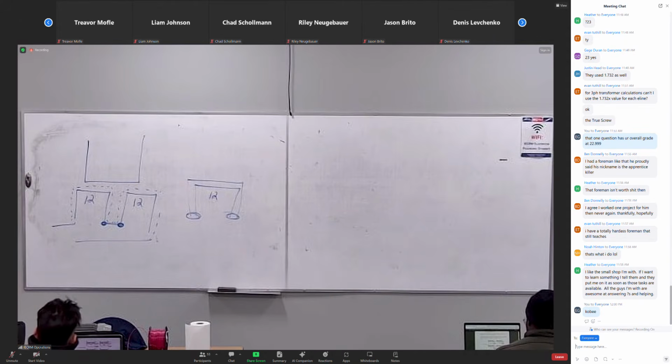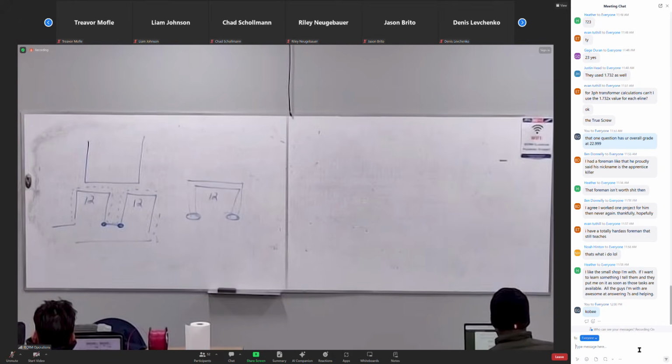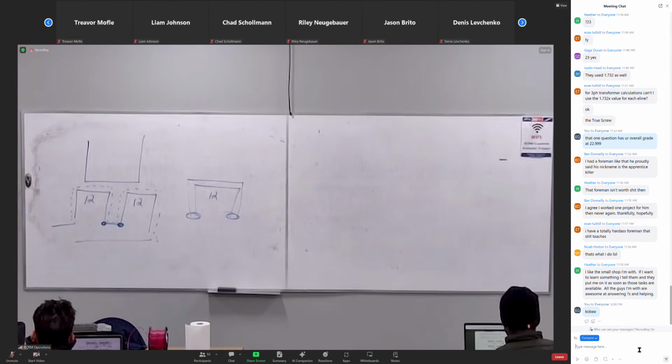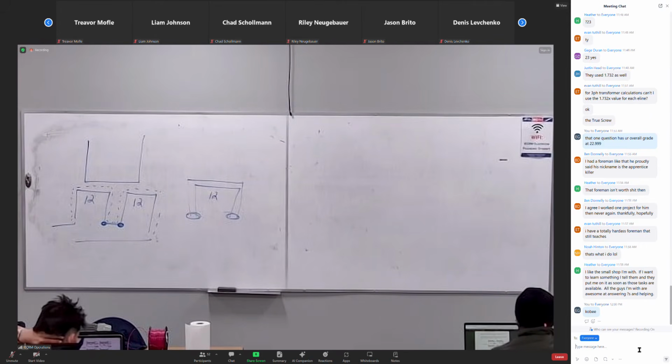120. If I want E1 plus E2 to equal 240, I have to connect them in what? Series. So that means I have to have 2 and 3 tied together. And the outputs would come out of what? 1 and 4, right? Or 1 and 1 as they have it over there. So yes, drawing number 1 or answer B would be correct. So if you look at drawing number 4, are you only getting 120 out of that diagram?